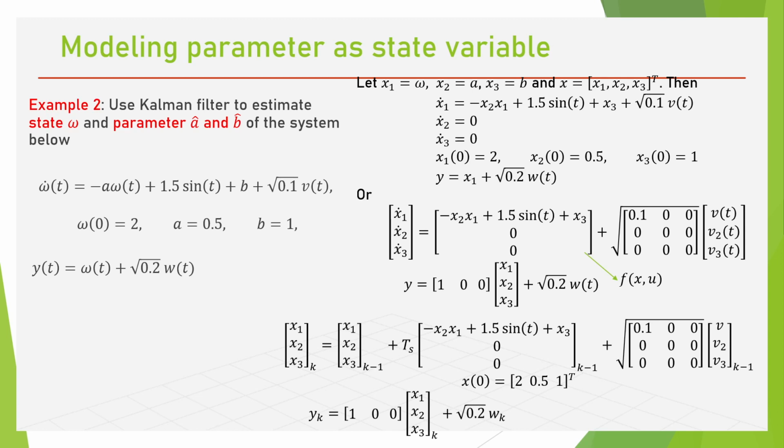For the output we use the data corrupted by noise, and then we implement a Kalman filter that doesn't use the same A and the same B. We just estimate any A, any B at the beginning, say all zero. We just know the model, so we remodel: we choose A as a state, B also as a state, h2 and h3, and rewrite the differential equation like this.